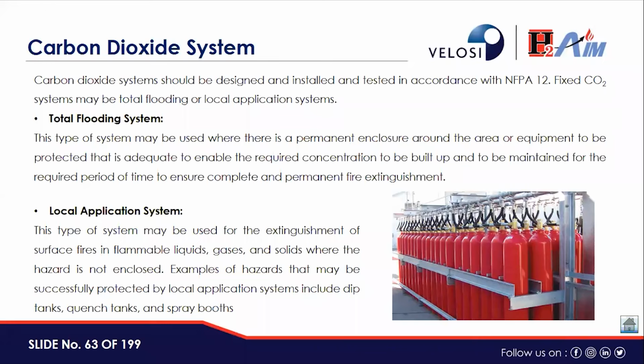This type of system may be used where there is a permanent enclosure around the area or equipment to be protected that is adequate to enable the required concentration to be built up and to be maintained for the required period of time to ensure complete and permanent fire extinguishment.